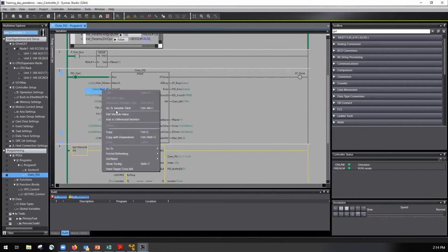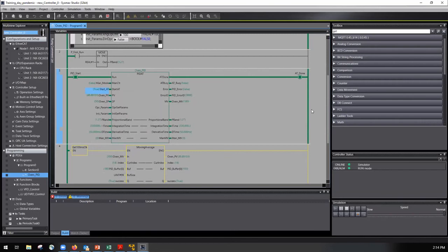Now I'll try my auto tune with that new parameter in there. So now if you look at my output, I am either 0 or 100. I am not gradually going in between 0 and 100. It's all or nothing. So very responsive.